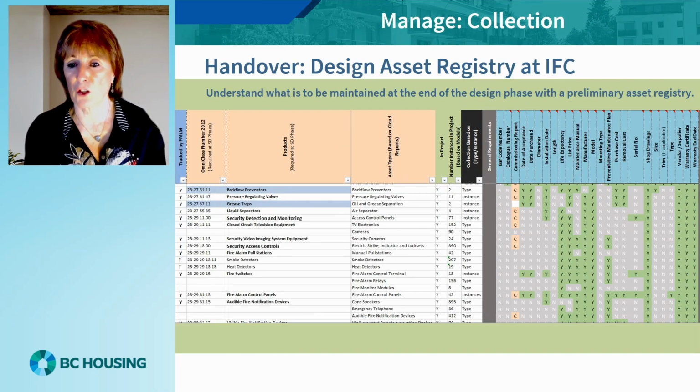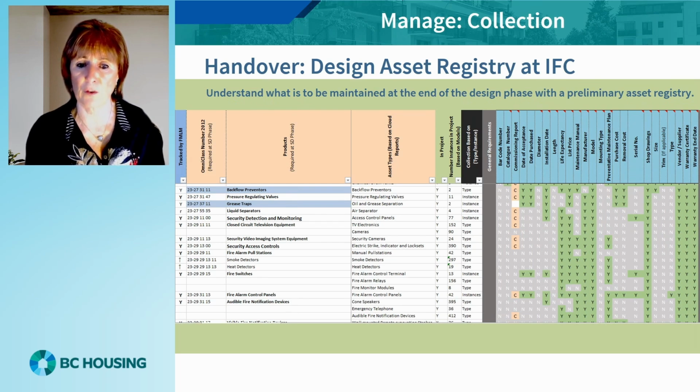The benefits of the digital process mean that at IFC, the dataset can provide a preliminary asset registry of all assets in the facility, along with the required installed asset information to be provided during construction. This preliminary asset registry provides an early understanding of what will require maintenance in the final facility. This required information is provided iteratively as the construction process proceeds, along with update of the design models to reflect changes during, not after construction, leading to a more accurate record model at handover.